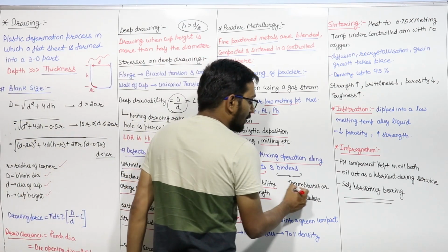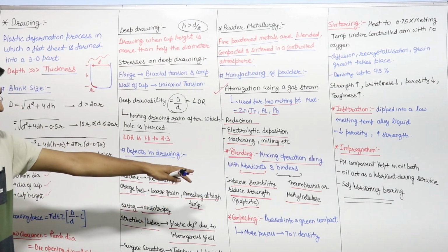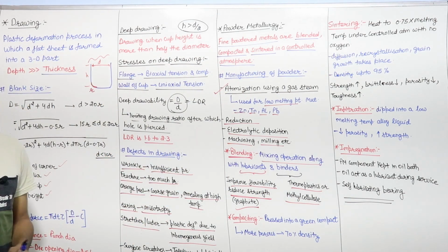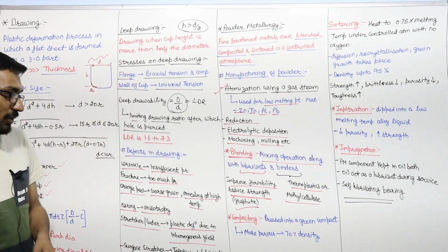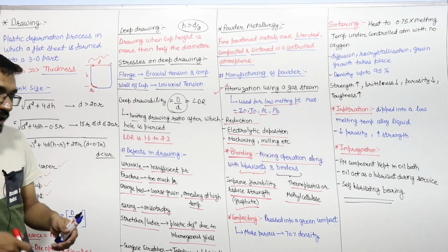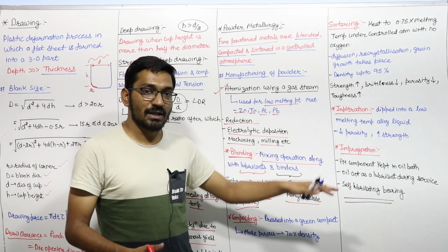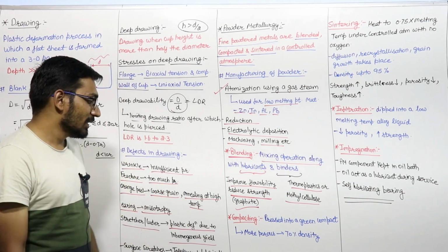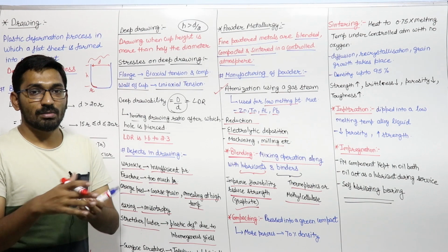Generally thermoplastics or water soluble methyl cellulose is used as a binder. Either you can use the thermoplastics or methyl cellulose. Then after the blending, we do the compacting. In compacting, we press it into a green compact. Because of this pressing, the powder takes the form of the cavity.